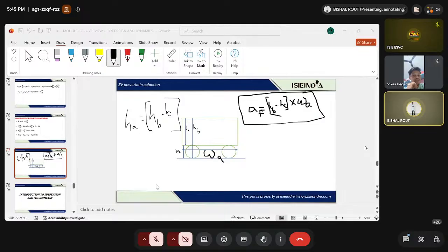Let us suppose I calculate it for 20. So I will increase the value in the slider up to 20, and then I will run. If I run, I will get a steady state speed. You can see over here, I'll get 44, right? So I need to stop these iterations. Here I will note 44 kilometers per hour.